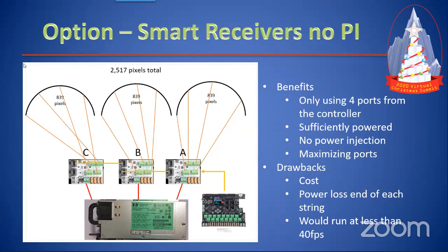That's an interesting one that we talk about, right? It is. I'll be honest with you, it doesn't hurt to fuse everything. Do you have to? No, but it doesn't hurt at all. If you're going to get a spike of higher than 30 amps coming through, the fuses on the board are going to blow or something else is going to happen, but it doesn't hurt at all. I used to do it on all of mine. I don't today, but it doesn't hurt.